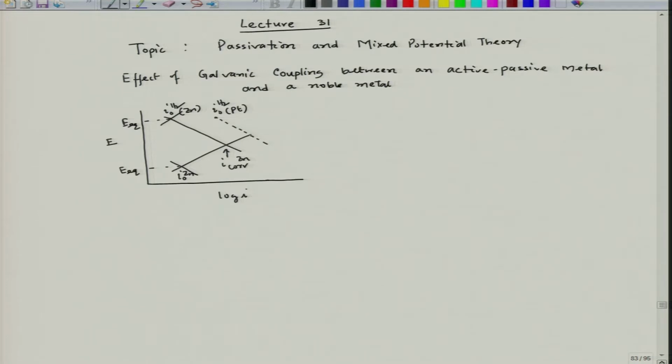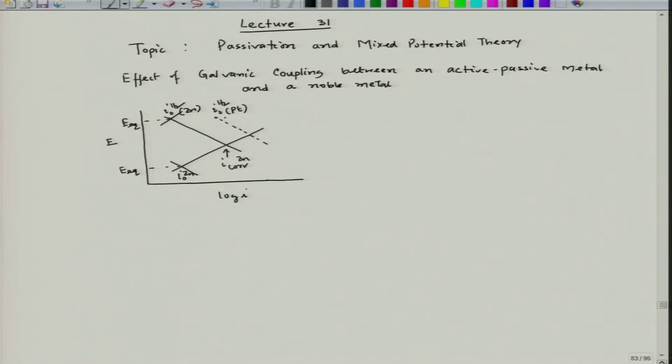it will have its own cathodic polarization, but you have to add all the cathodic current densities and see a mixed potential point where your total rate of cathodic reaction is equal to total rate of anodic reaction. So, that is what we always add, that particular hydrogen evolution reaction on zinc surface, and that goes like this.